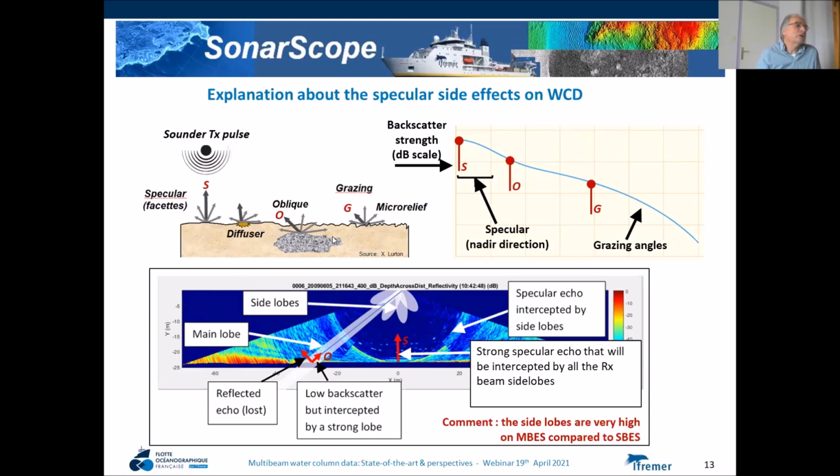When we are not in a specular situation, a small quantity of energy is backscattered to the sounder. This is due to the roughness of the seafloor or shells or small objects laid on the seafloor. These objects have many facets oriented perpendicularly to the sounder.